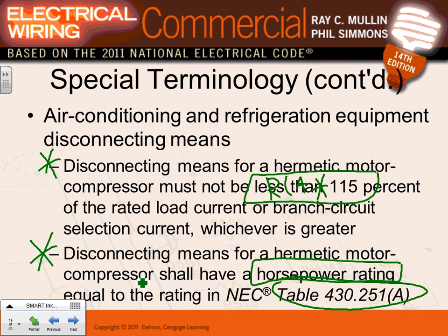Okay, so when you have a disconnect, guys, your disconnect is going to do the following. Here's my disconnect, and here's my equipment. It's going to have two sizes. This disconnect is 30 amps and rated for 10 horsepower. Can you guys see the two sizes? Amps and horsepower. Amps allow the current to go through it. Horsepower allows you, in an emergency situation, to interrupt the energy, load interrupter, so it doesn't blow up in your face. This is typical for motors, guys. Motors are the same, like these. Exactly. It has to have two sizes: amps and horsepower.